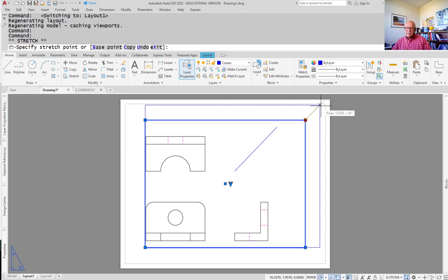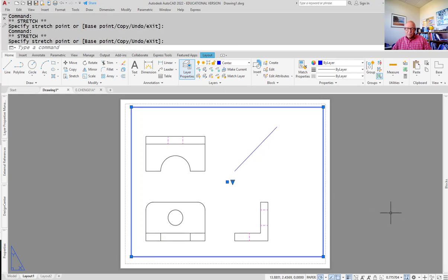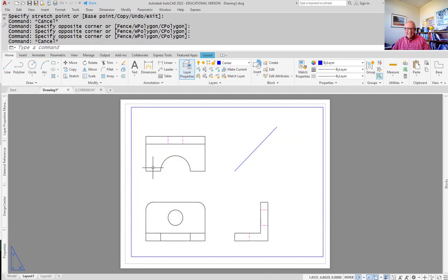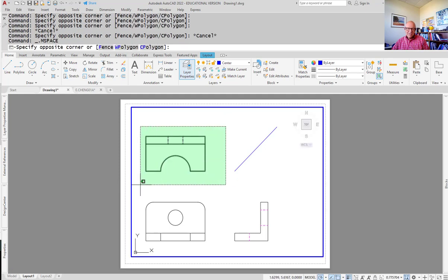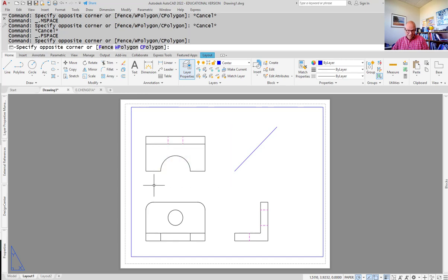This is just called a viewport, and that viewport is simply a view of what I've been drawing. It doesn't allow me to select anything down here unless I make it active. So that little viewport is like putting a window on top of a sheet of paper. Open the window, you can reach out and grab stuff. Close the window and your hand bumps into the window before you can grab stuff.